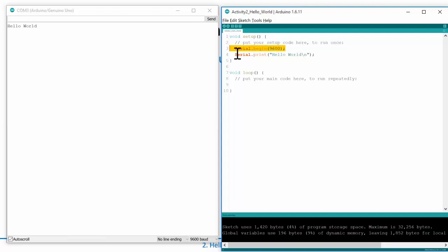The next one that you're going to use a lot is a print function in the Serial class or the Serial library that's just called .print. And the way this works is it's really powerful because if you put print, inside the parentheses, if you put double quotes, you're going to put text. Okay, so if I type hello world, it'll type hello world over here on the console. And when you do Serial, what it means is that it's going to type that as ASCII characters that are sent back up the cable and are put in the serial monitor.